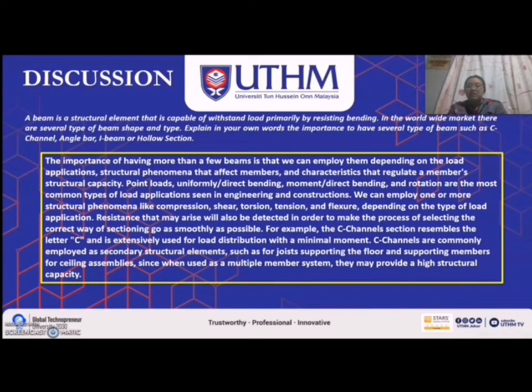So now I will explain the importance of having several types of beam, such as C-beam, C-channel, angle beam, I-beam and hollow section beam. The importance of having more than a few beams is that we can employ them depending on the load application, structural phenomena that affect the members, and characteristics that regulate a member's structural capacity. Point loads, uniformly distributed loads, direct bending moment, and rotation are the most common types of load applications seen in engineering construction.